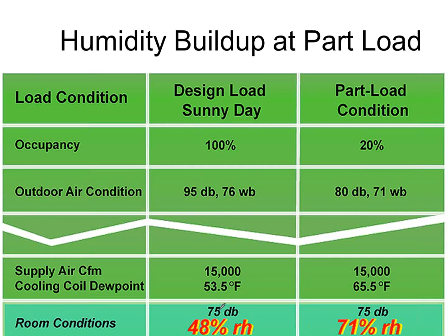However, on a regular 1 or 2 stage package unit, what ends up happening is really the right-hand column. Well, it's probably not fully occupied. It's probably partially occupied, or it's not really 95 outside like rooftops are designed for. It's really like a more typical day in Chicago, 80 degrees outside, which means I'm cycling my compressor on and off, or my compressors, if I have 2 of them, on and off.